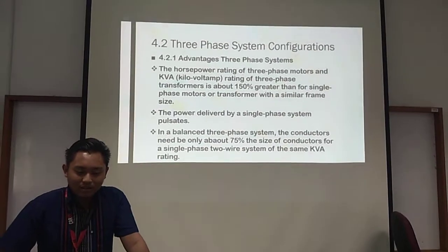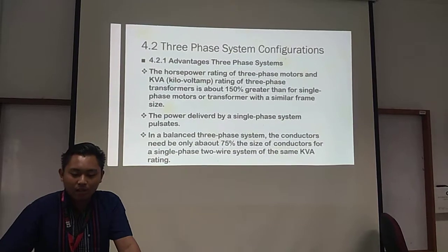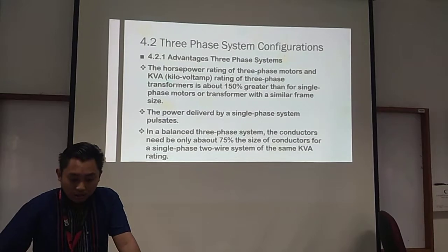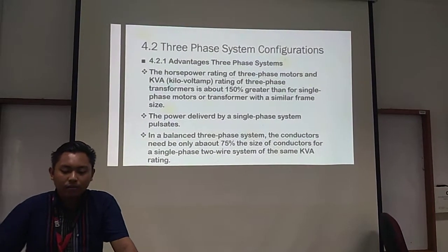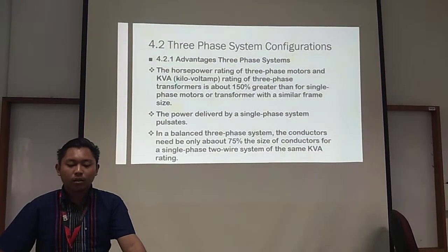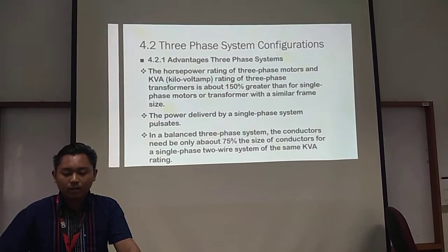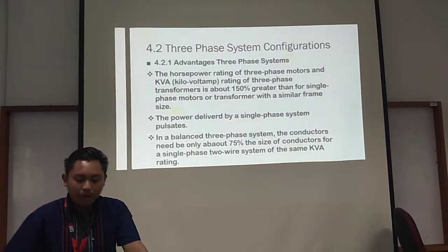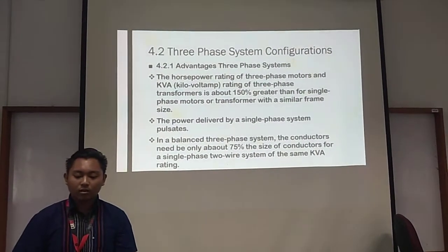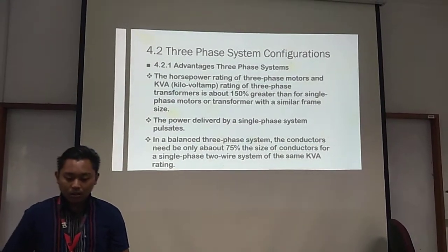I will talk about three-phase system configuration. Advantages of the three-phase system: the horsepower rating of a three-phase motor and the kilovolt-ampere rating of a three-phase transformer is about 150% greater than for a single-phase motor or transformer with a similar frame size. In a balanced three-phase system, the conductor needs to be about 75% the size of the conductor for a single-phase two-wire system of the same kVA rating.